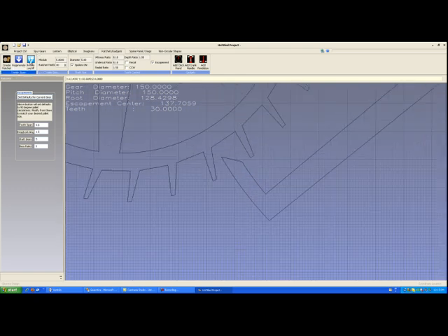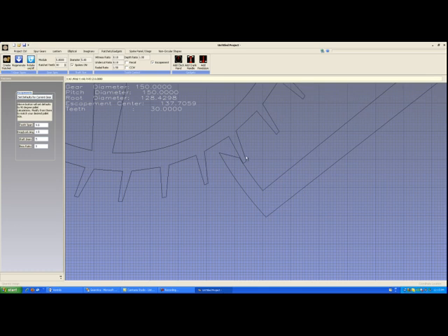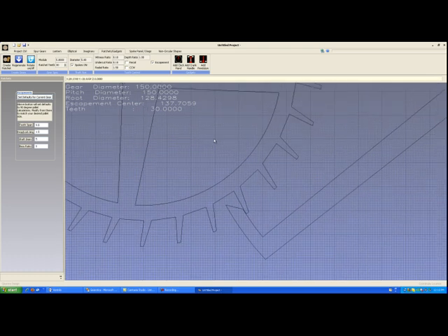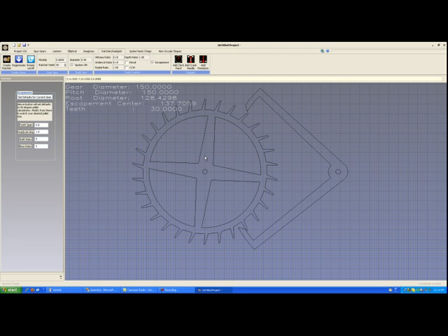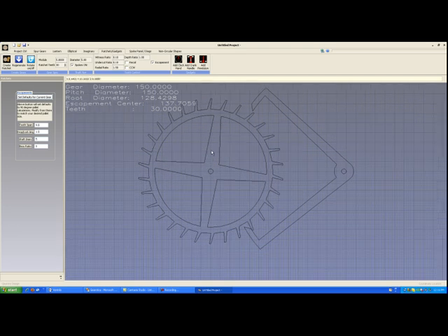If we hit rotate, you'll see that last drop was probably about 1.5 degrees. I say about because I'm trying to point out to you that this drop lock angle is not an absolute figure. It's really giving you a name to work with, and it's adjusting quite a few variables just to ensure that the drop does change, but that we maintain other parameters as they should be.